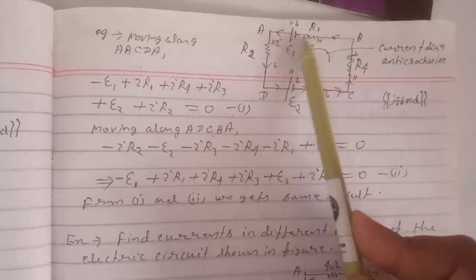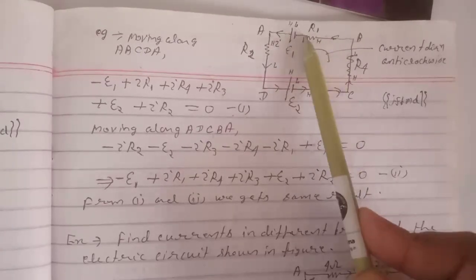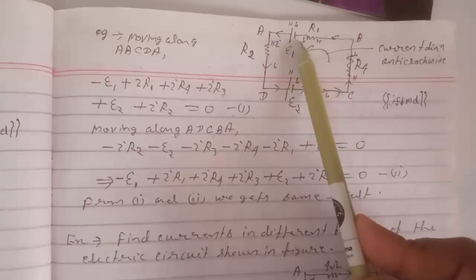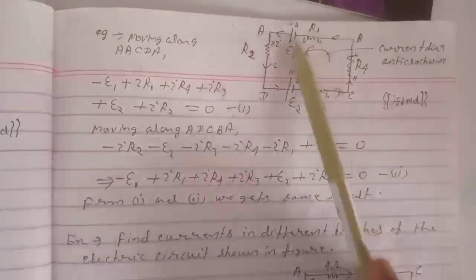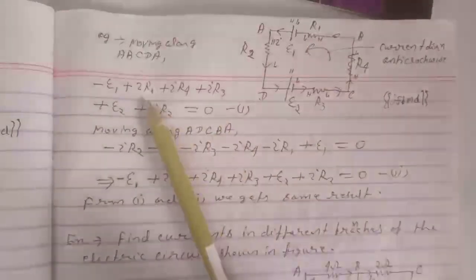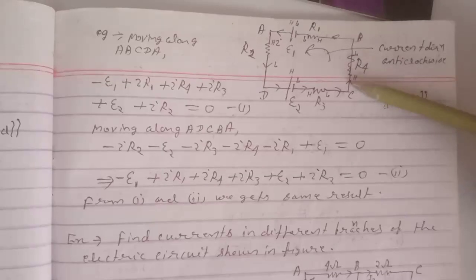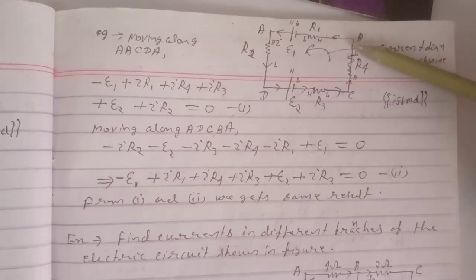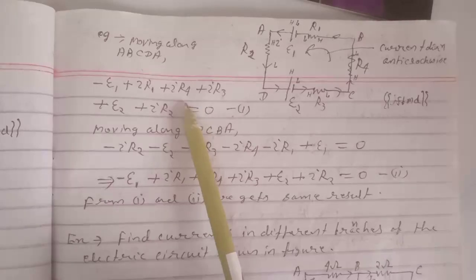Now we are going from here to here, so final is at higher and initial is at lower, so the potential difference across will be positive, given by I into R1. We are considering that current I is flowing in this circuit. Again here, final is at higher and initial is at lower, so final minus initial is higher minus lower, positive, I into R2.